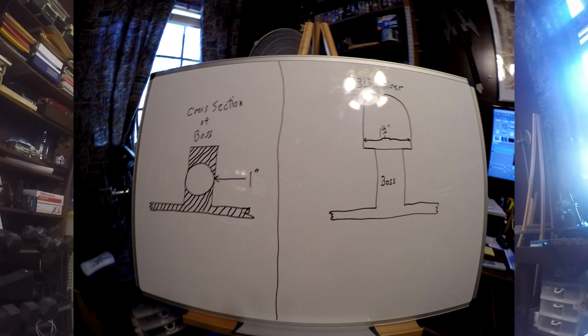One technique that you can use to make certain that your riser has the hottest metal, if it's open to the atmosphere and you're pouring your casting: as soon as you see that the metal is starting to come up into the riser, stop pouring, go directly to the mouth of the riser and pour directly into the riser.